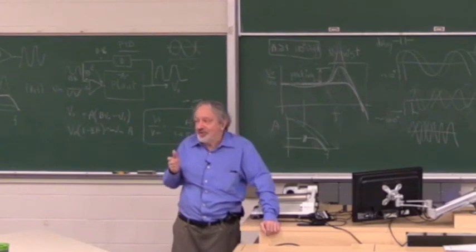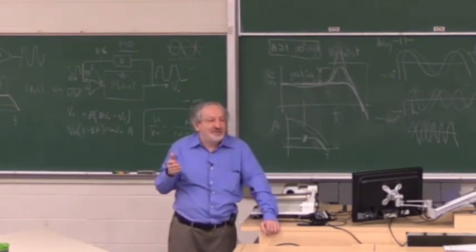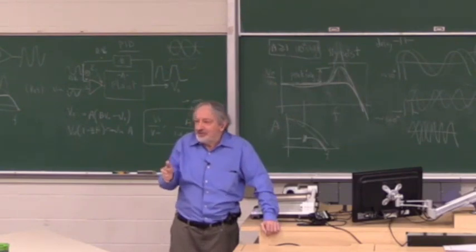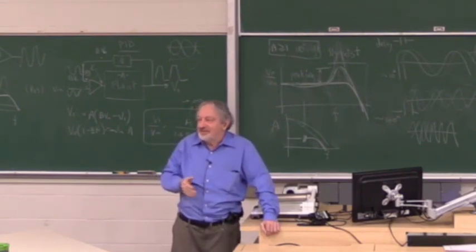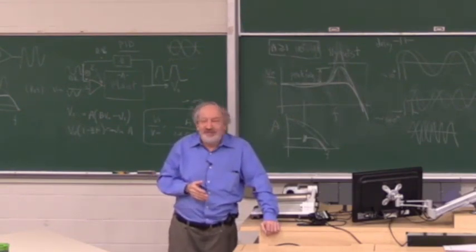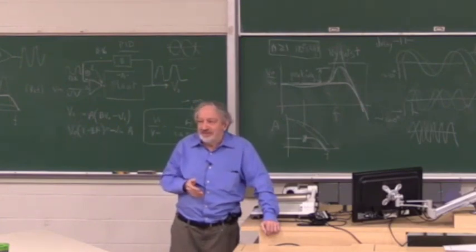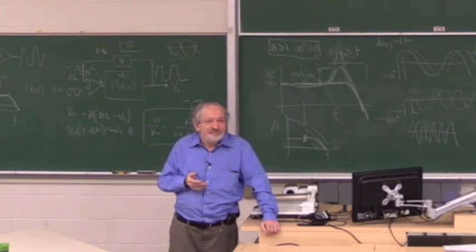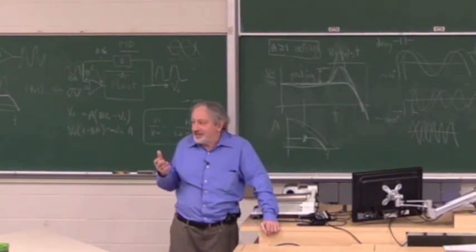Okay, so is a resonance a first order system, a second order system? Second, good. And what happens to the phase in a second order system? Because in a second order system you draw amplitude and you draw phase. So what happens to the phase in a second order system? That's a mathematical question. It has nothing to do with servo. Okay? The phase changes 180 degrees.